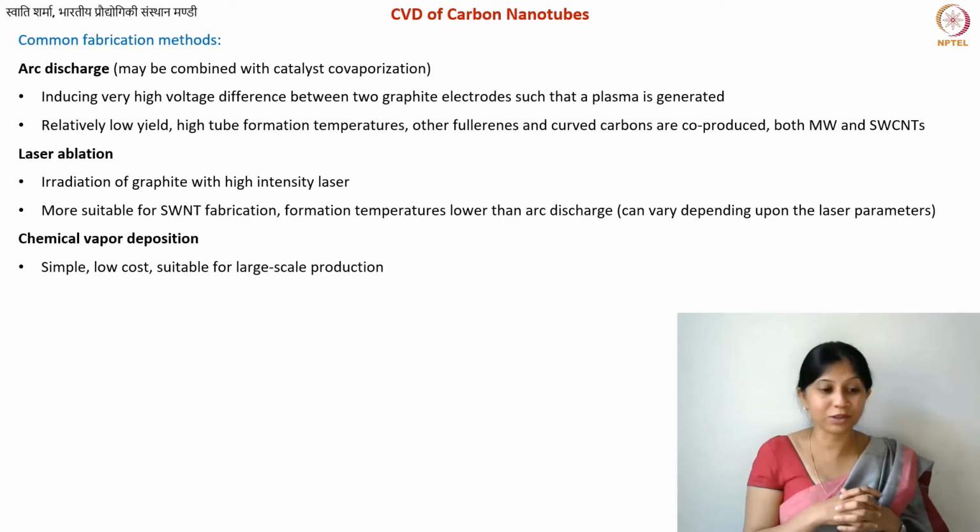And that is why also the carbon nanotube production has become relatively much easier in the recent past. Okay, so anyway, catalysts, how do you prepare? So do you always have to have particles? Sometimes you can also have particles, but not just made of one metal, but made of alloys. And that is how you can play with the geometry of your carbon nanotubes, basically by modifying your catalyst. Most of the other things are very similar to what you will have in the case of graphene.